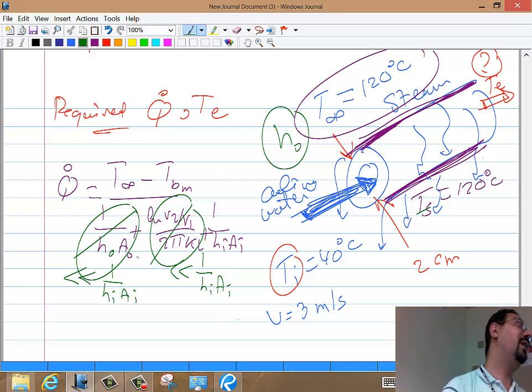Well, same thing on the outside. This particular problem, you didn't really even know the velocity on the outside. How are you supposed to calculate the Nusselt number and treat this as if it's convection, for example? So you were not given the tools. That's for practical purposes. And physically, you should know that conduction resistance is much smaller than convection. And also, boiling and condensation resistance is much smaller than convection. So in the future, when we have boiling or condensation on the outside, assume 1 over H out is always going to be negligible.